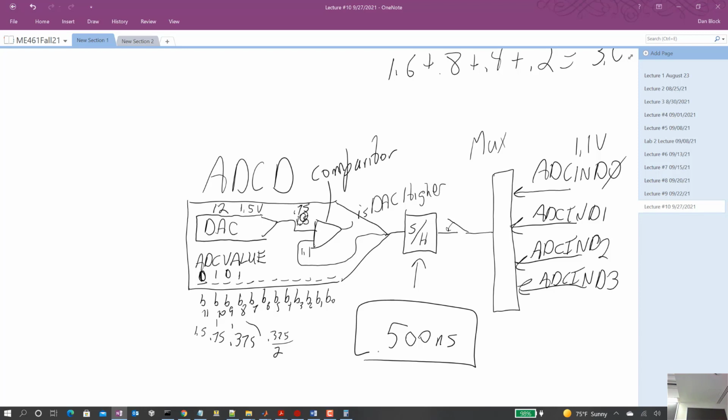Technically, and that's what always gets people, and I call this Arduino programming, you could tell it to sample, and you could go read the results register immediately. The issue is, what's sitting in the results register? It's the value you told to sample 1 millisecond ago. You're getting a 1 millisecond old value, and in most cases, that's not a big deal. In my class, that is a big deal.